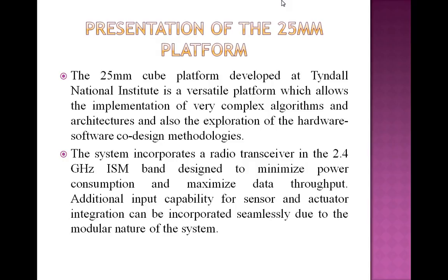The embedded microcontroller for this platform is the ATmega128L. This is an 8-bit microcontroller with 128K bytes of in-system programmable flash. The user can easily program the device with custom protocols. The Atmel microcontroller can be programmed to operate in sleep or power down mode, awaiting activity on an interrupt pin. The wireless transceiver consists of a fully integrated frequency synthesizer, a power amplifier, a crystal oscillator, and a modulator.